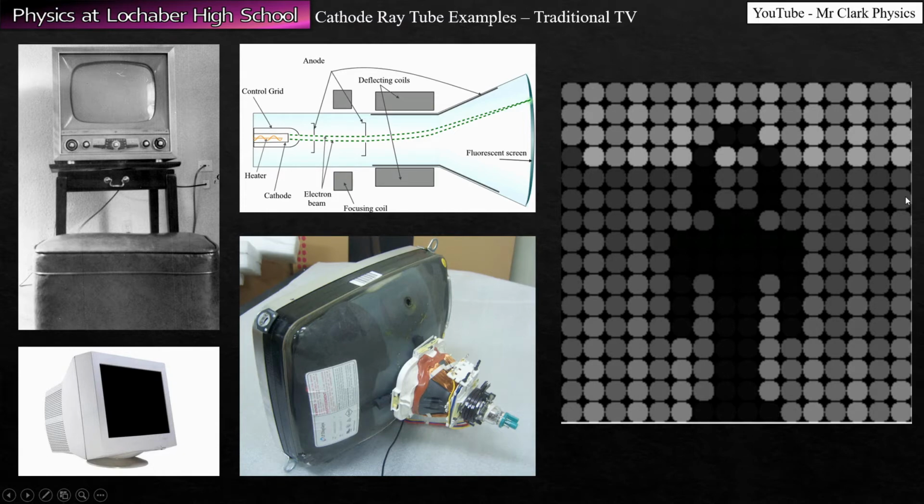By blocking the electrons partially or wholly, you can turn the brightness of the different spots to different amounts, and that's enough to produce a black and white image. This whole cycle, this whole frame needs to be painted 30 times a second. So our electron gun scans across really quite quickly with a pair of coils that are at both sides. The simple thing, which is quite nice though, is it doesn't matter which picture you're showing. The pattern for scanning this gun is always the same.